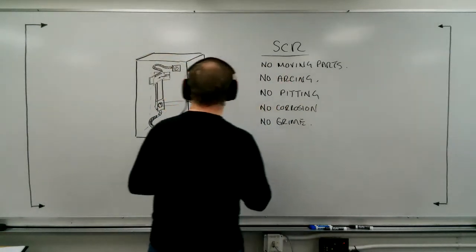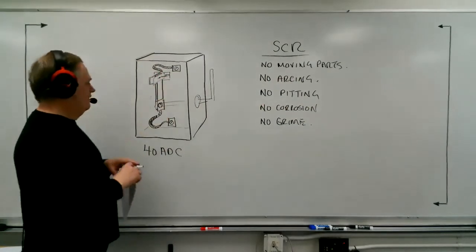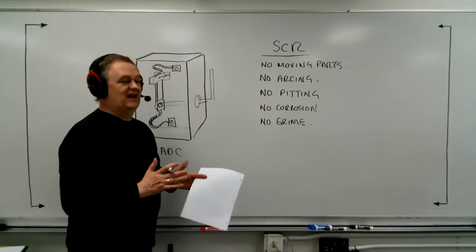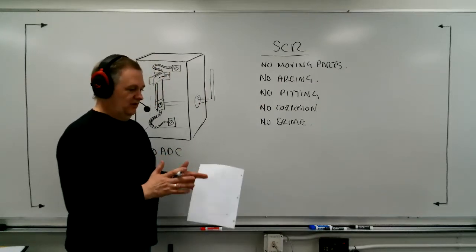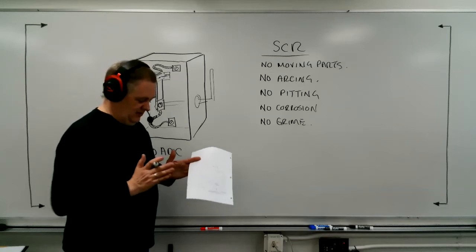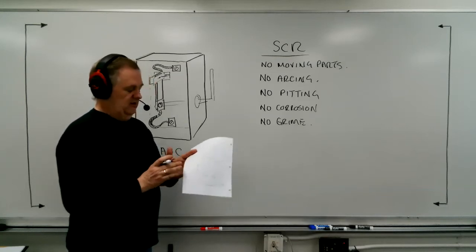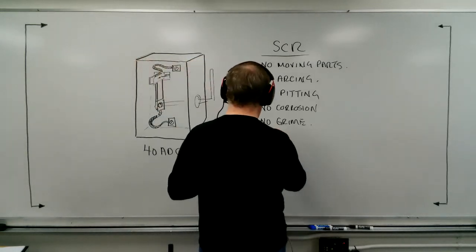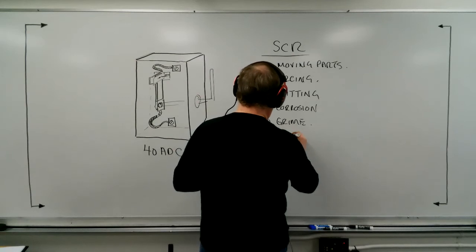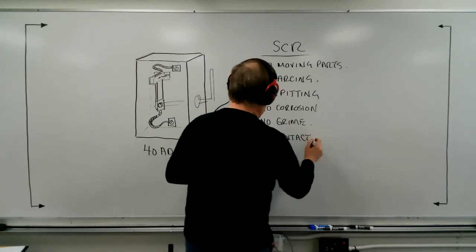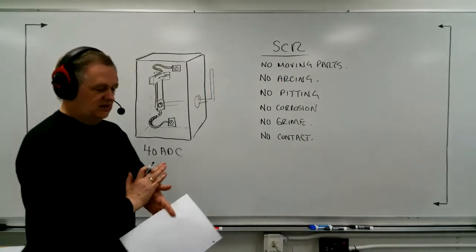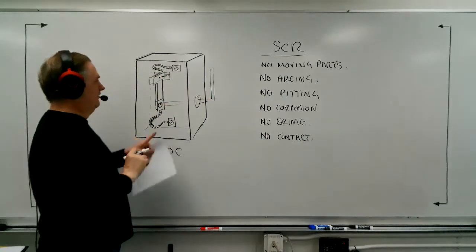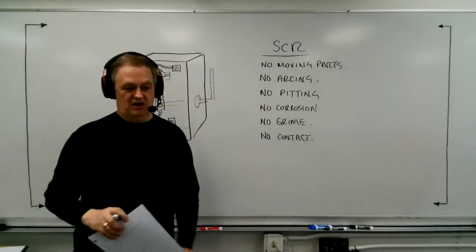Another thing that happens, not so much with these switches but with contactors, where you have a mechanical, magnetic contactor that is closing and opening, is that when the spring hits, they would sometimes cause a contact bounce. That bounce creates an arc. One of the things we say about the SCR is that there's no contact bounce. It's just firm and positive: the current starts, the current stops. Absolutely none of the issues that happen with this switch will happen with the SCR as a switch.